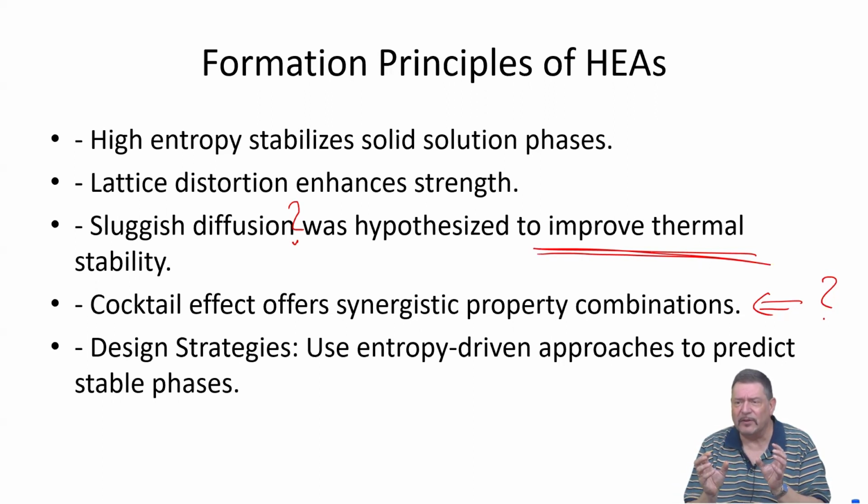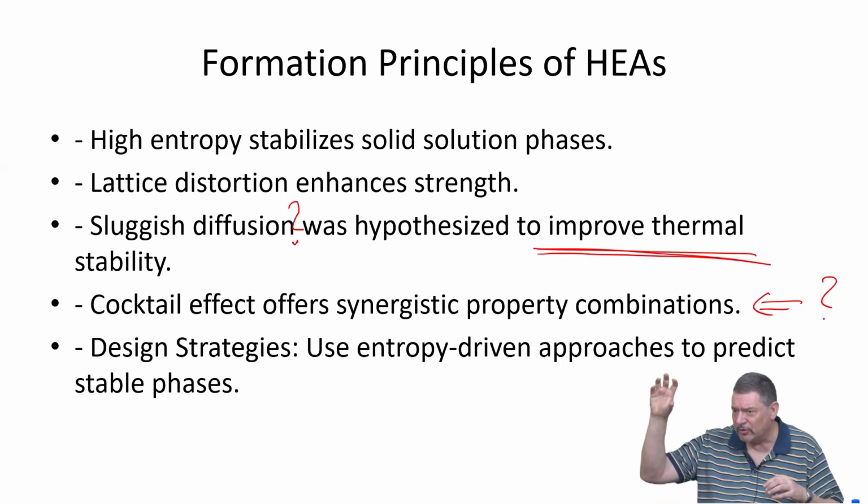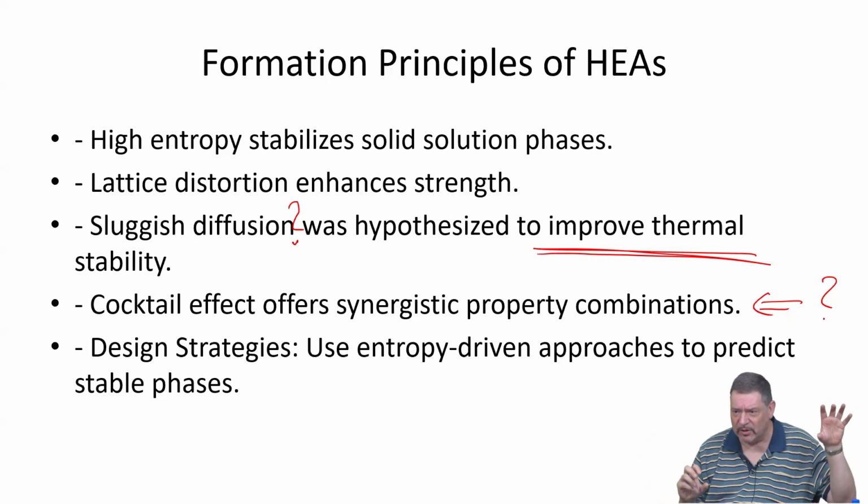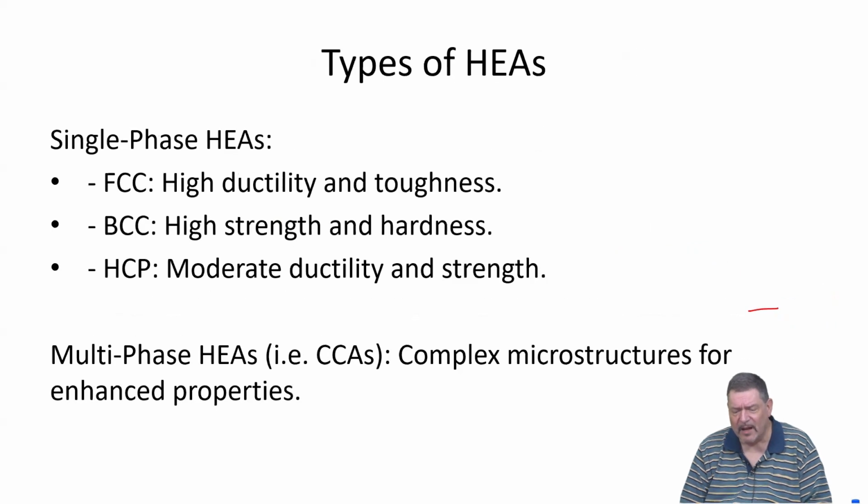The elements cannot be too different in terms of their electronic structure, their electronegativity, their effective radius in the alloy. Otherwise, you will not be able to form a solution, because then the enthalpic term overwhelms the entropic term in your thermodynamics. So far, as I am aware, in the metallic systems, single-phase high entropy alloys only have been found for these.